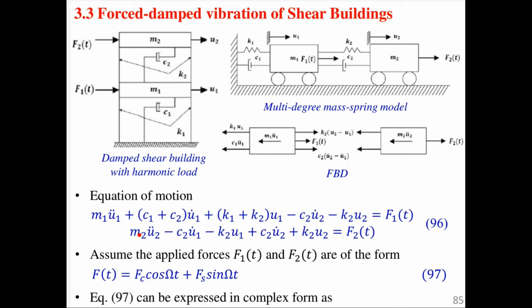So if you compare with the other equation we had previously, what we are adding is the component of the damping and the velocity. Be very careful with this dot, because this represents differentiation. This is the velocity, this is d over dt. This is the acceleration, so it's d squared u over dt squared. So we have included the damping, F1, F2.